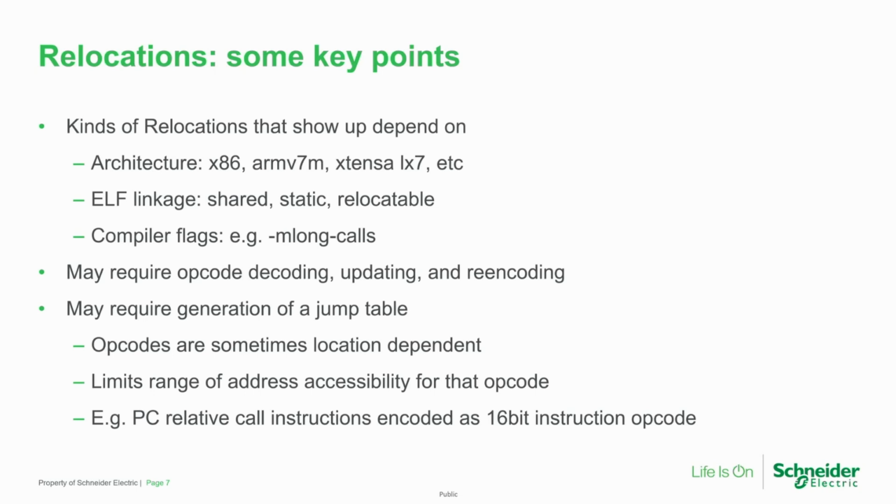There is also a different way to do it. If you don't want to actually parse the whole code, because it can be very time consuming and takes a lot of time on your product to just load the application, you can do some kind of partial link, and then you have to use a jump table. So basically your code is using a table. The table, you don't know where it is yet, but when your product starts, you just copy the table at some place and then patch it with the correct addresses. So your code which has been loaded knows the jump table and can use the new addresses. Not too many details, of course.